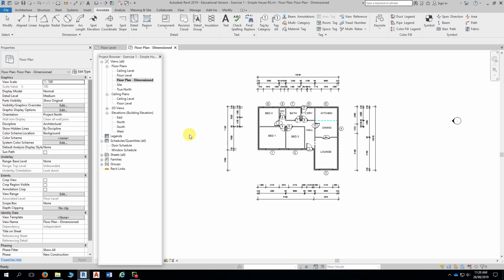There may be reasons why you need to see above and below. Mainly it's below. It's sometimes advantageous to see what's below our current level in case we have to trace it for some reason, or just work out the relationship between what's in our current level to what's in the level below. So in this case, we use it to show the roof.